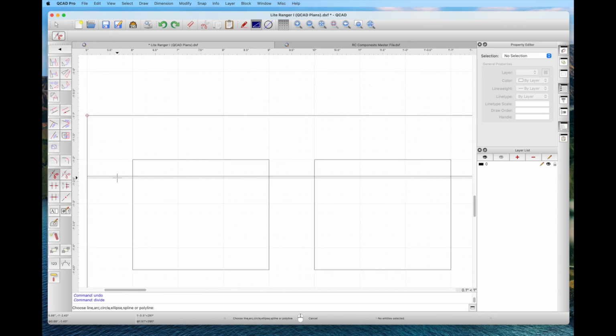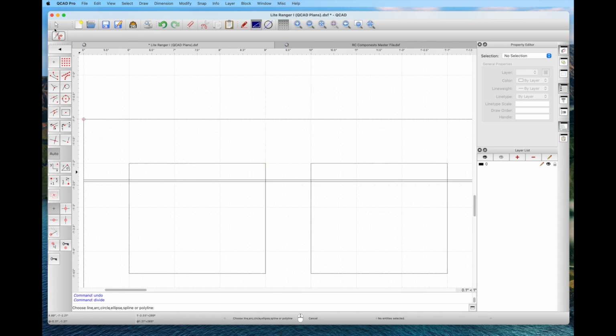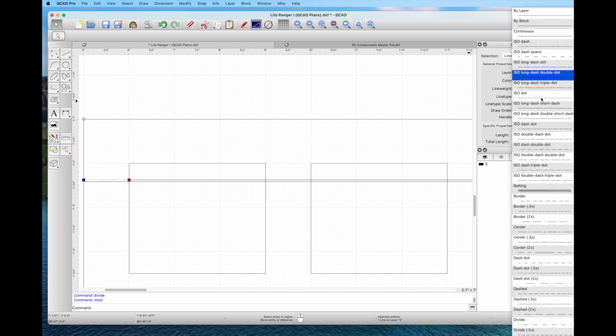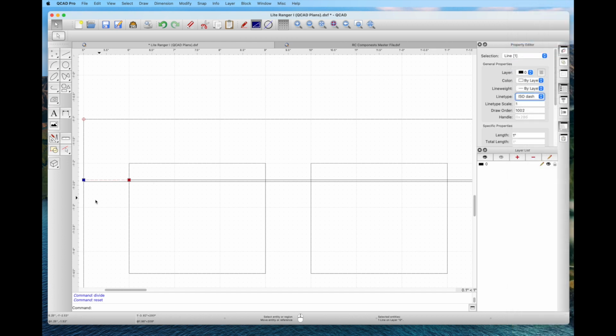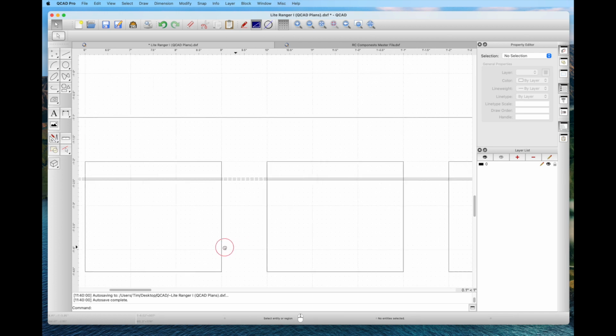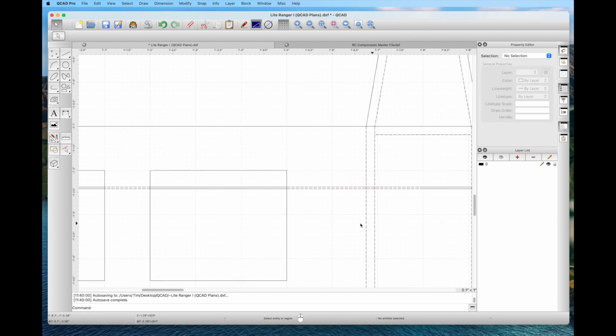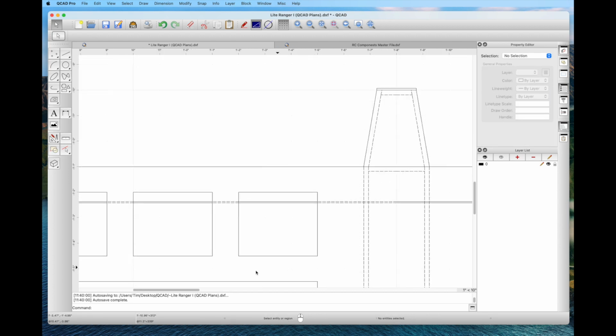And again, we're going to use the divide tool. I won't go through everything because it's repetitive. We select the line, go to the intersection, so we can take that long 15-inch line and divide it into segments, because portions of the carbon rod are under the foam board. We want to select those with the property tools and make that a dashed line just for clarity of the drawing. And you can see this is just repetitive how it flows. If the rod is underneath the foam, it should be a dashed line, just the way you draw the plans.